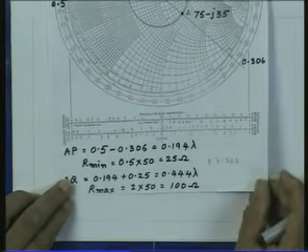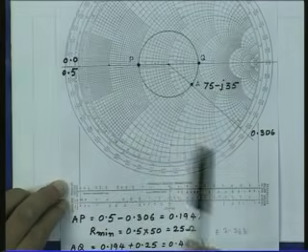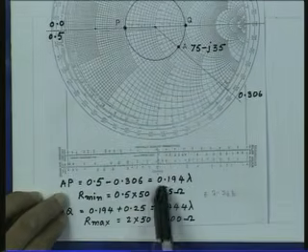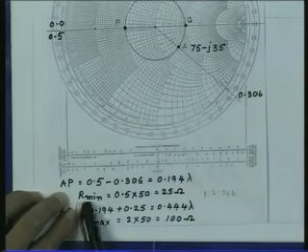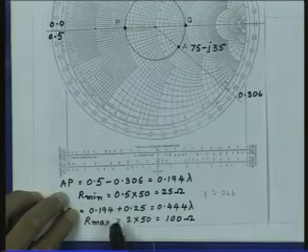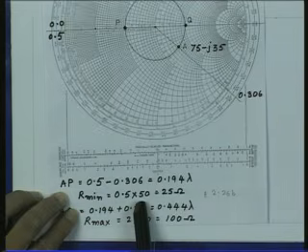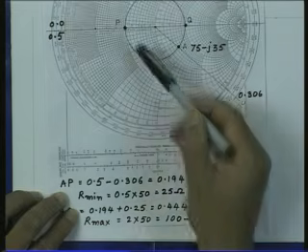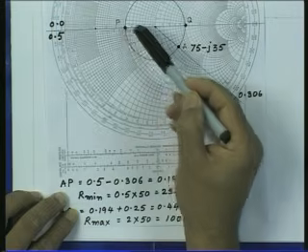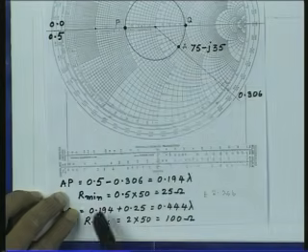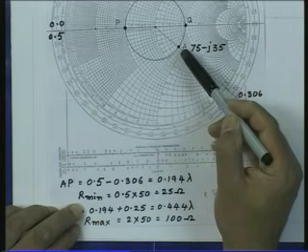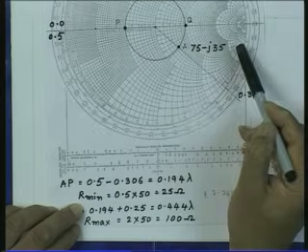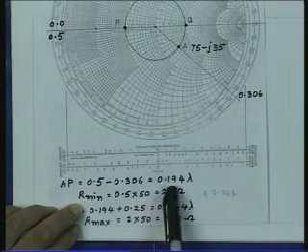So, one possible solution is that if I take this length, then that length will be 0.194 lambda and the impedance to be matched will be R min, and that will be 50 ohms multiplied by the normalized value here, which is 0.5. So now I get the impedance to be matched will be 25 ohms if I insert a length of line between the load and the transformer of 0.194 lambda.